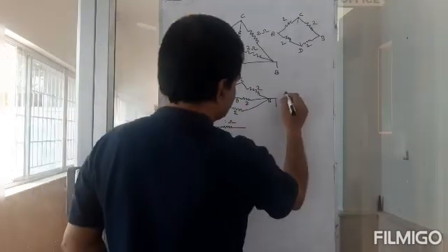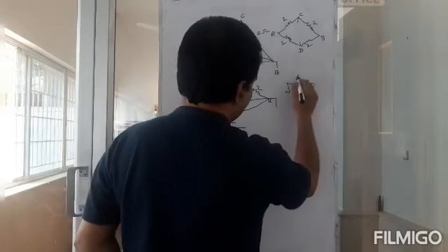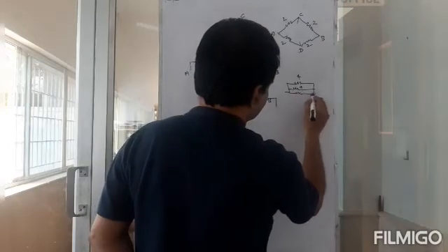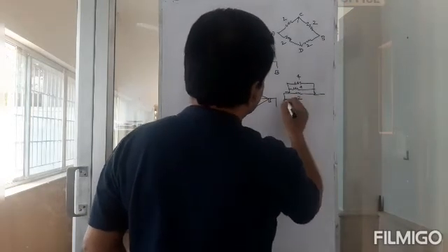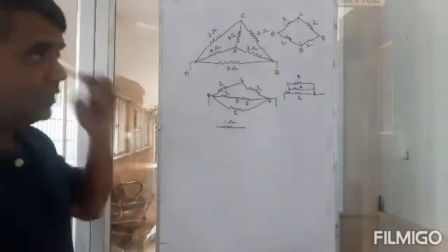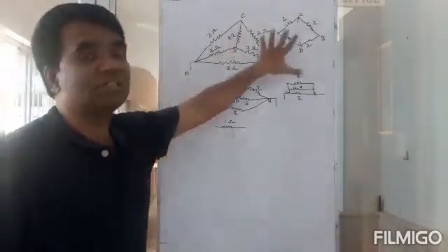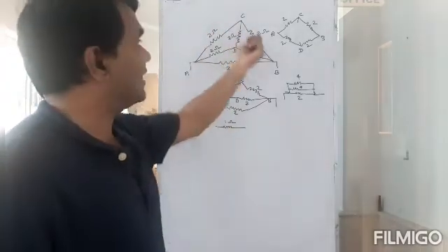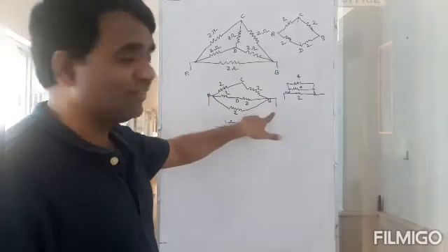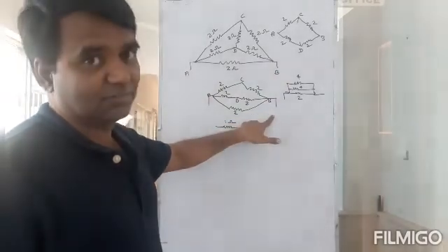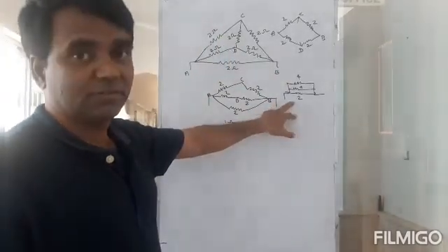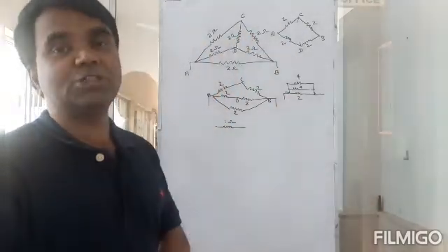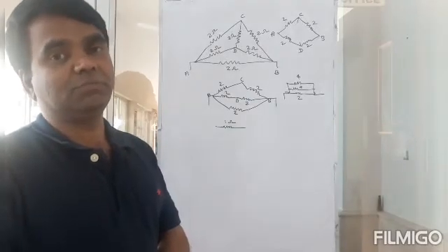How? Note here. So it's like this, right? This is 4, then this is 4 again, and this is 2. The effective resistance will be 1, because this condition is met. But if they all have different resistances, the balancing condition may not be met. In that case it will be difficult. But in this case, it will work, because you are using the Wheatstone bridge balancing condition.